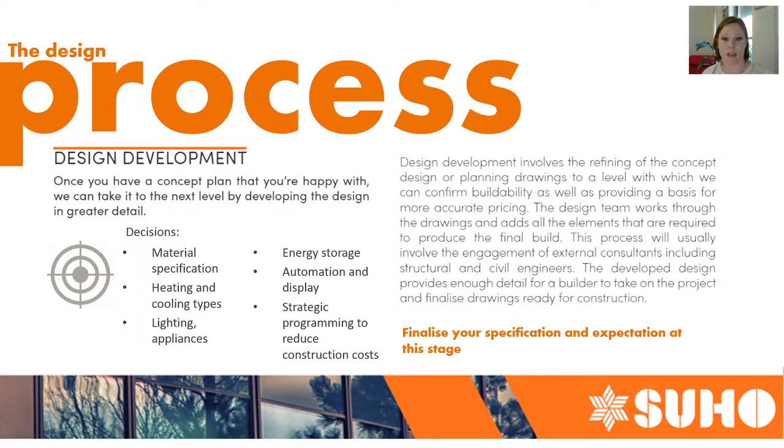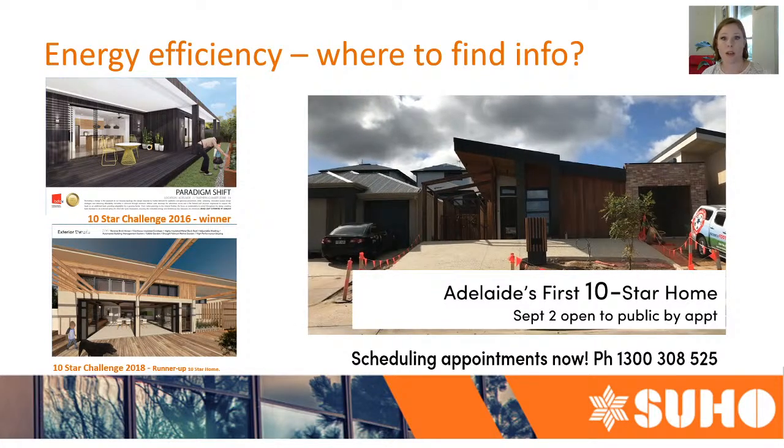The other thing that we are learning more and more about is strategic programming to reduce the construction costs. That also is tied into potentially where we're using thermal mass. We have learnt through different projects that analysing the house based on a standard construction and adding the thermal mass on the inside strategically just in certain points rather than through the whole building is a really good way of keeping down construction costs, and the studs can run straight to the outside of the buildings.